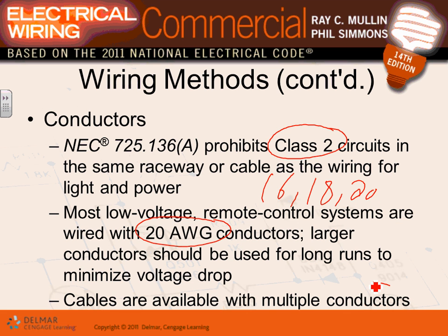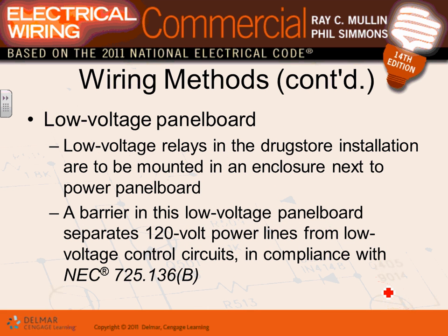What they do is they have multiple conductor cables, and typically they have a common to the switch. You can have one common, and every switch, guys, needs at least 3 wires, right? So you have one common and the other one on, off. You'll see them. But the common one can be shared between multiple switches. I'll show you this one in a second. Any comments, guys, about the type of wiring that they use with the low voltage control system? It's called class 2 circuits. It's limited in the voltage to 24, limited in the power. Power limited, voltage limited.